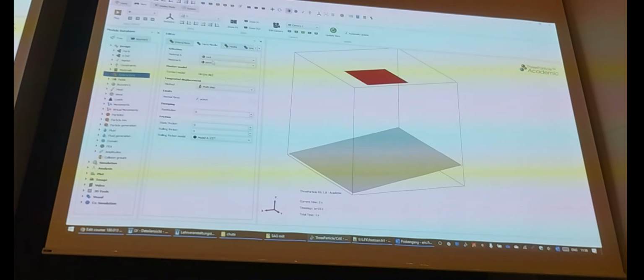We have material A and B, steel. A lot of stuff to go into, but as you remember, what this might be, restitution. You remember? Particle falling from a certain height, jumping back. Let's give that 0.2, for example. So I want to have something like that. A little bit of damping, not too much, not too little. Something between 0 and 1. So it's the restitution, that jump back of the particles.